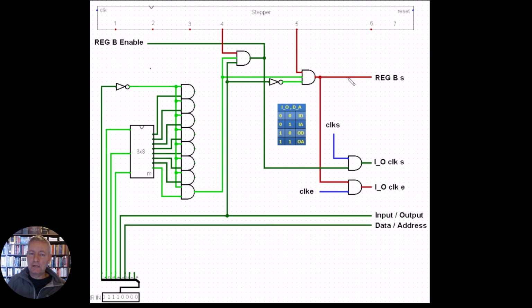So it's going to be Reg B, and it's going to be either 0, 1, 2 or 3. So we're going to have to set that information into the register. So the set will go high and then low, and that information will be set into that register. And again, we're going to have to clock that information in. So we clock it in via this line here, and this is the clock enable, and this goes out to the IO clock enable.